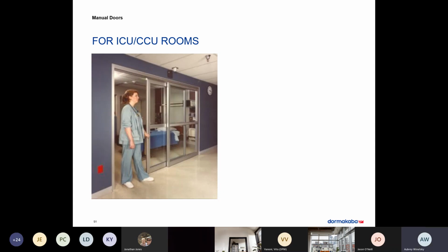I would say if you're coming across these doors, really find out what the requirements are. Like in California, we have OSHPD, which is a whole kind of governing body that dictates different rules that apply just to healthcare in California. Whereas, most places you need a 32-inch opening.